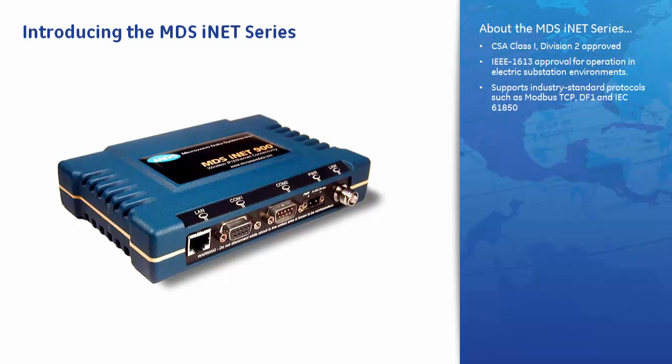MDS iNET transceivers meet some of the most demanding product specifications in the industry. The product is approved for use in CSA Class 1 Division II environments, has IEEE 1613 approval for use in electrical substations, and it supports industry standard signaling protocols including Modbus TCP, DF1, and IEC 61850. The iNET is designed to be as plug-and-play as possible, requiring a minimum of setup for initial operation.